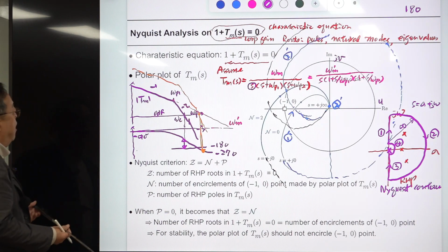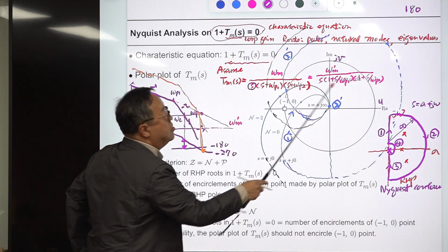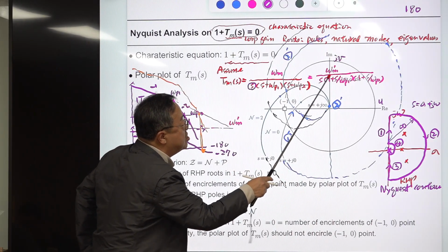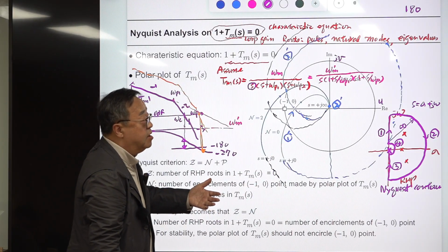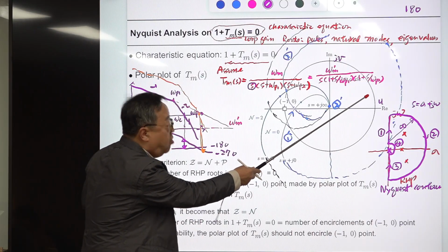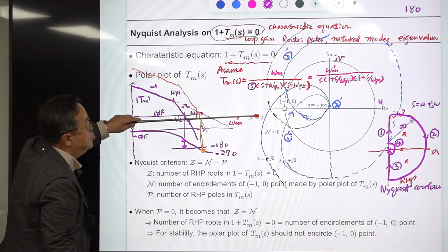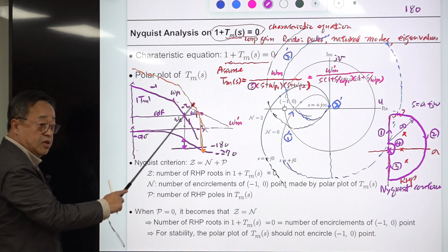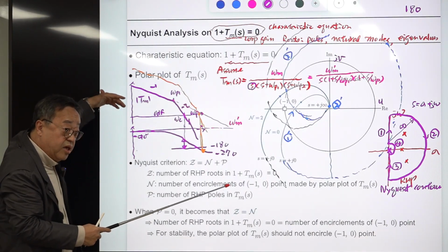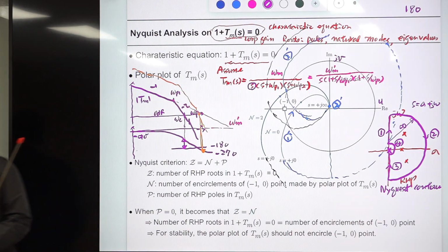And there is another system. You increase this. You don't change the numerator or denominator; you just increase omega m prime 10 times, 100 times, something like that. That means the phase remains the same because phase is not changing. By changing this constant, only the magnitude is increased, so the magnitude curve will be raised in parallel, in this way. It starts from here, and omega p1 was here, so the same omega p1 will occur here.